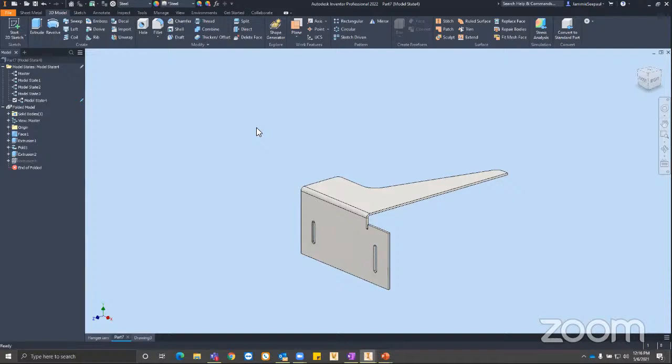Okay, yeah, that's useful. So everything's done through feature suppression. Does it still support... Because I know when you're modeling inside of a generic Inventor component, you can move around when features occur. So, for instance, if Extrusion 2 wasn't reliant on specific geometry that came before it, you might be able to move Extrusion 2 all the way up to before Face 1. Is that something that model states will still handle? Yes, you can definitely do that.